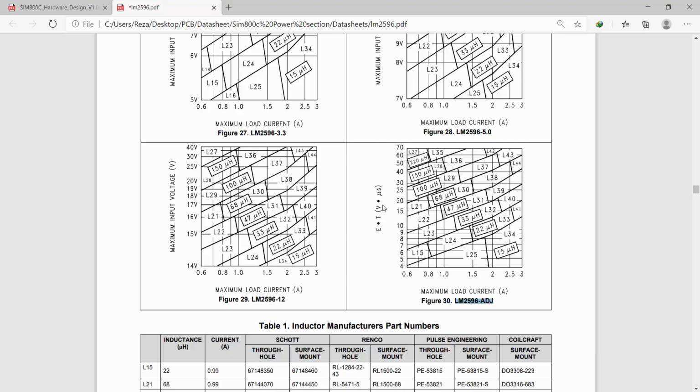Its value is 18.22 volt microsecond. Our maximum load current, as I said before: our GSM module draws a 2 amp current when it's going to connect to network, but in this case this current is not continuous. It just happens when it's going to connect to network. Our continuous current is the current that will be drawn by our GSM module in normal situation, and our indicator LEDs. It's something about 1 amp.